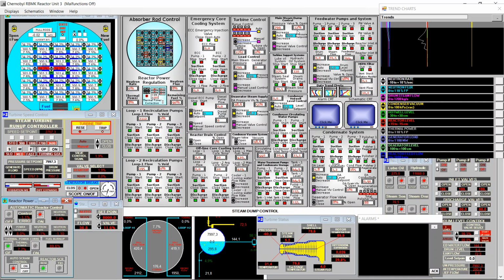Okay, the relief valve is closing. It's at almost 10% now. So I will reduce a bit more the power set point. Let's go to 7. Relief valve at 9%, 8%. We can see here with 1 decimal point. 6.9, 6.5, and I think we will get close to 0 without closing it totally, so it looks to me like a good value, 7%.